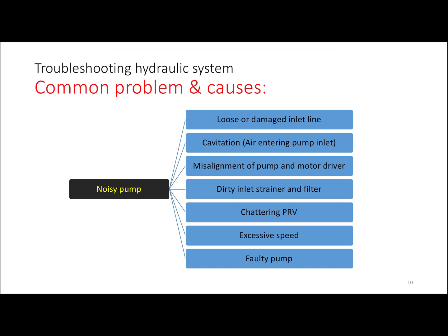It also can be because of misalignment of the pump and the motor driver, which is the installation of the pump itself. Also, it can be because of a dirty inlet strainer and filter. Also, it can be a chattering pressure relief valve, something wrong with the pressure relief valve. And also can be because of excessive speed of the actuator. The worst thing is because the pump is already faulty. In total failure, meaning you have to dismantle the pump.